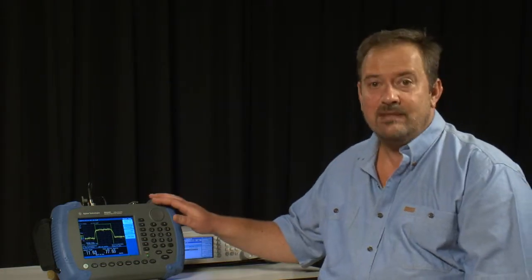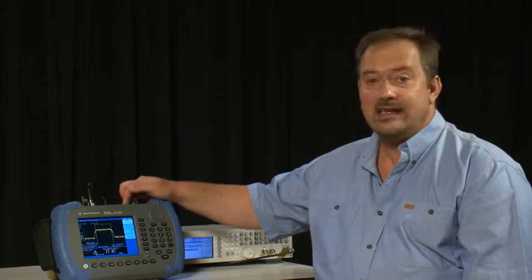When out in the field, we don't want to have to set up each measurement from scratch every time. So let's see how we can use the N9344C's save and recall capability to save and recall instrument states, and also how to save a screen capture of the measurement results for including in a report, for example. Here I'm going to be saving files to the analyzer's internal memory, but be aware you can just as easily save and copy files to and from a standard USB memory stick that you insert into the top of the instrument. Let's start by saving the current instrument state into the internal memory so we can quickly recall it the next time we're out on site.